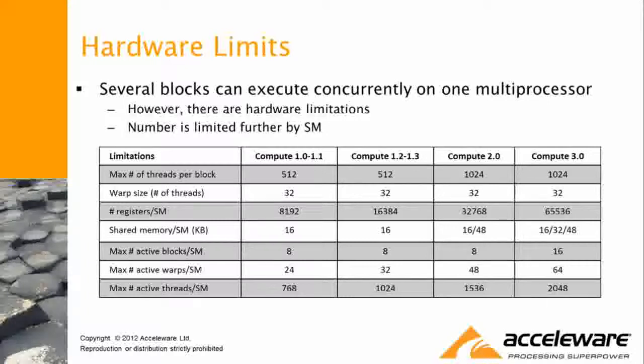Okay, so the maximum active warps per streaming multiprocessor, that's this number here. I don't actually think the slide deck talks about it, but this is the denominator of the fraction which they call occupancy. Occupancy is simply a percentage. So for example, if I was able to get 24 warps on my streaming multiprocessor, I would have 50% occupancy. Now you might say, I want 100% occupancy. Yeah, you probably do actually, but we'll talk about that in the next couple slides. So the idea being that you want to get as close to this 48 as you can to maximize your throughput of the GPU so that you can eliminate the GPU from stalling. Always keep the GPU busy.